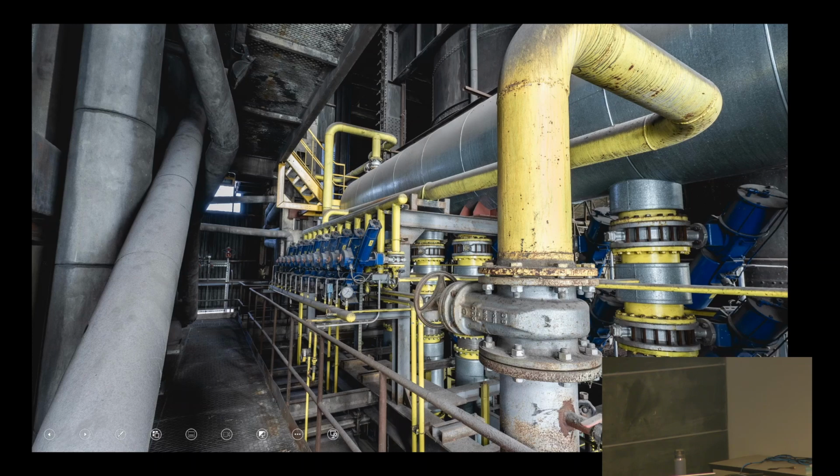You can a priori, so ahead of time, design all this in a computer. So if you work in this sort of industry, you will come to know these codes and standards quite well. There's also usually the company standards that govern what has to be placed where. The placement of things like these control valves would be decided probably by some sort of chemical engineer working in this plant that wants to have, say, control over the flow there. Or like this manifold here, it's important to be able to adjust whatever flow is going into this drum.